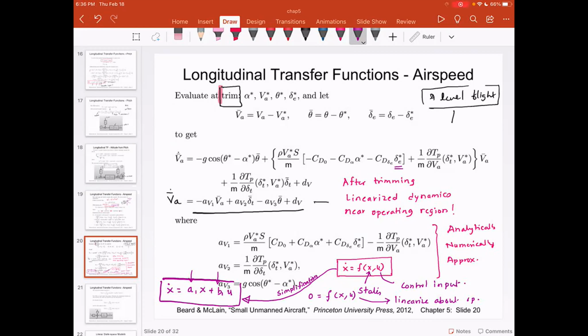We will take super complicated nonlinear equations and we will use Simulink to perform numerical trimming. We'll start with some simple equations first, perform the trimming or linearization by hand, run that through Simulink, see if our answers are correct, and then begin with a complicated set of nonlinear equations given on the Genesis block and come up with the trim conditions.